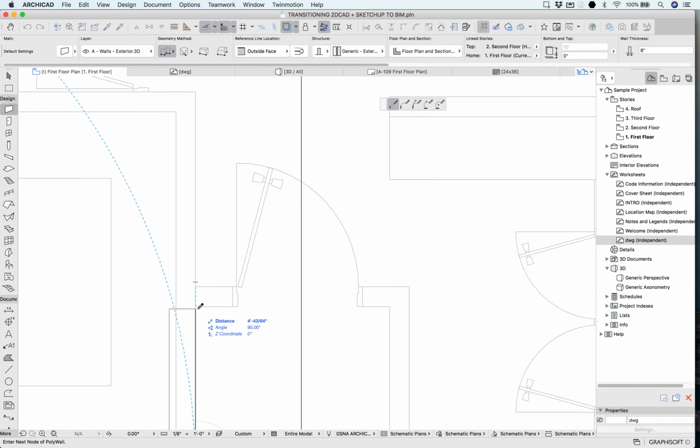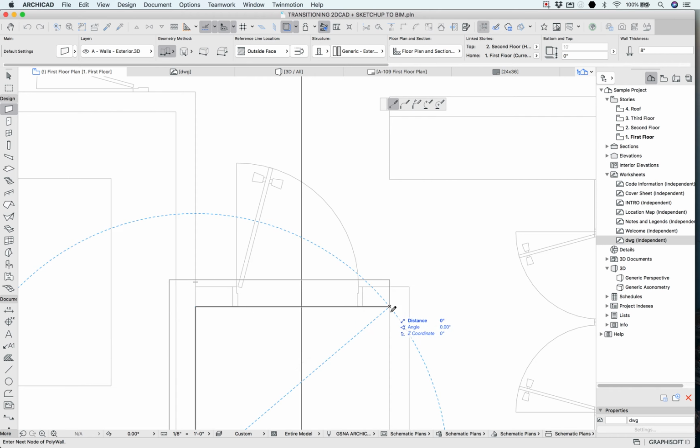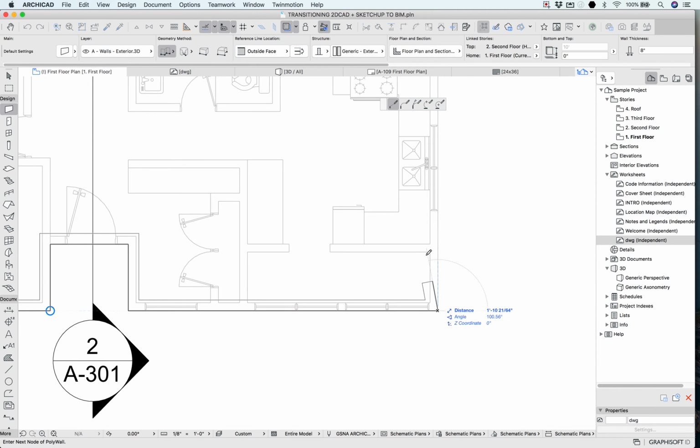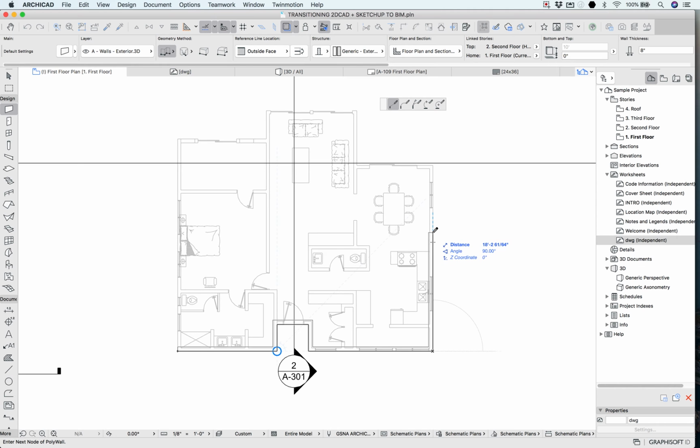And then what you'll notice is, you're going to be possibly tracing right in this element, and we can change the thickness of this wall. But at any time when you're drawing this, and I don't want to draw this entire structure here, you can always switch between different geometries. You don't have to exit the tool and come back. And then you can also use backspace in order to go back to the last node in that line in case you've made any errors.